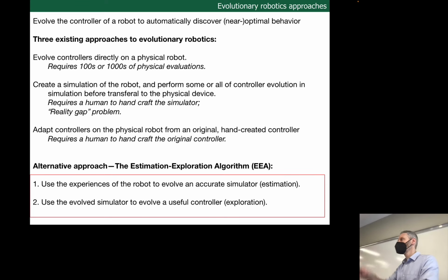Friction, collisions. Maybe the frequency of time steps. Frequency of time steps, getting the amount of time that elapses from one time step to the next, super, super hard to get right. If you have a simple simulation, you can get away with big jumps, and you can do a lot of physics in a relatively short amount of computational time. As that simulation becomes more complicated, you need to shrink the time step to make sure everything is accurate, but how much to shrink it, very, very difficult to know how to do.